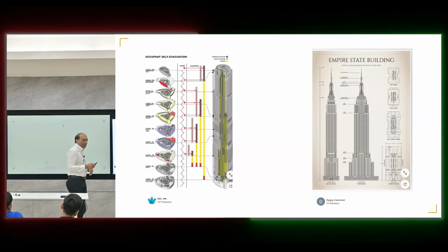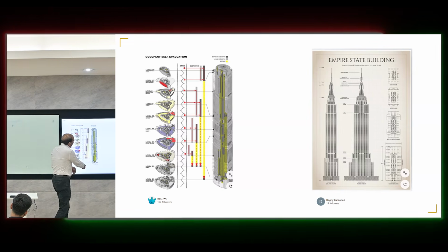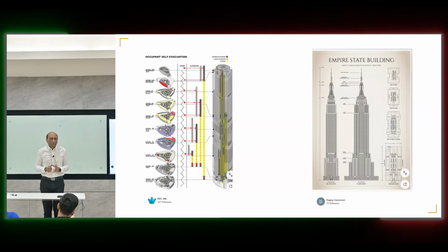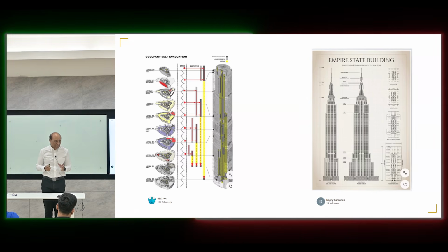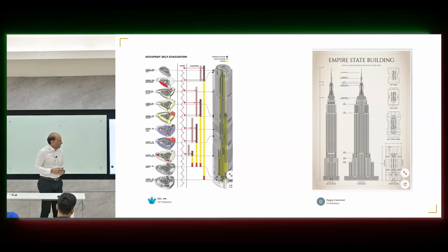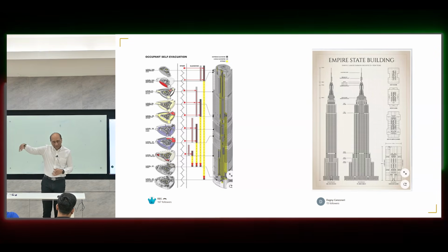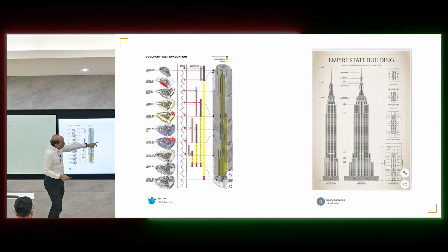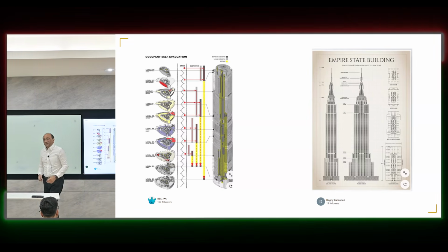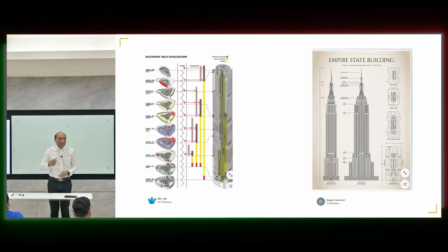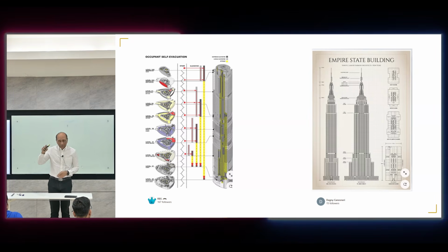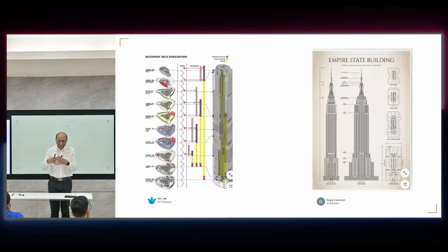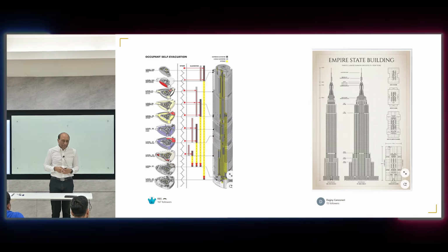So you cannot see it, but there's a whole evacuation system working within a tall building, and that takes a lot of the core space, which you cannot even access normally, only in an emergency, because you cannot have external fire doors or fire stairs. And that was one of the problems that was noticed in the World Trade Center. You might have seen the videos, people coming down were not safe from the fire, because that portion at that time wasn't developed properly.